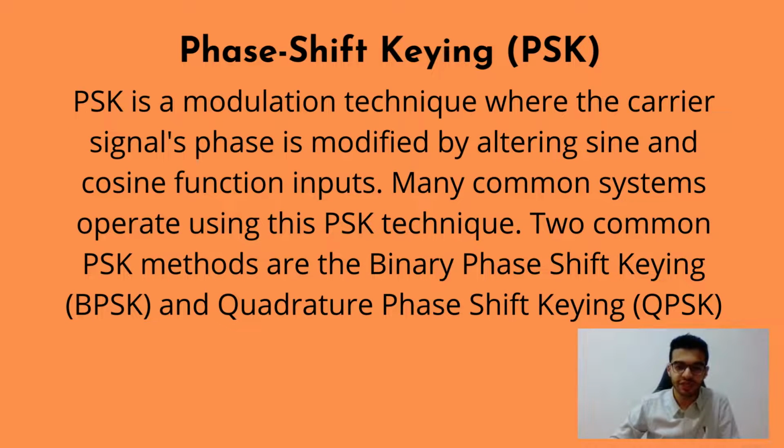Greetings, my name is Sharik Faisal and I will be explaining the phase shift keying modulation technique, which basically modulates or modifies the carrier signal's phase, the sine and cosine function of it. It's different from PM, the phase modulation, because it's a digital method. There are a lot of applications of this technique, such as wireless LANs, biometric connections, Bluetooth, RFID, etc. There are two common PSK methods: the binary phase shift keying method and the quadrature phase shift keying method.